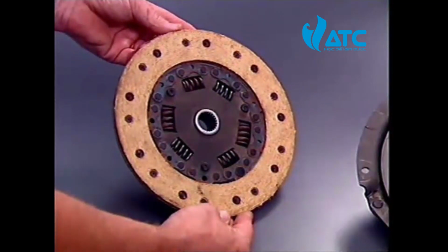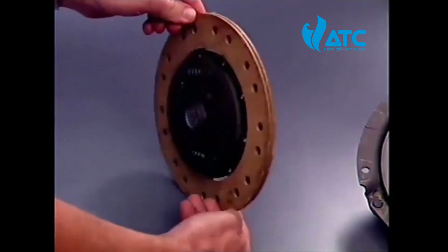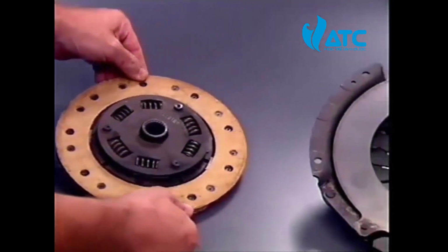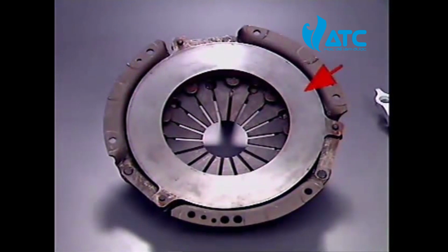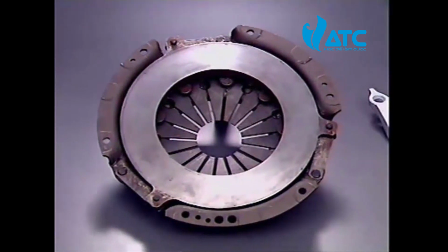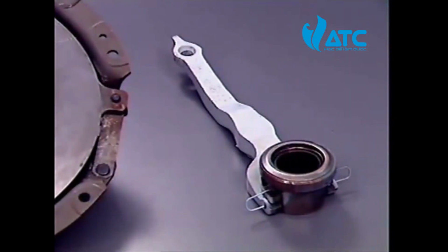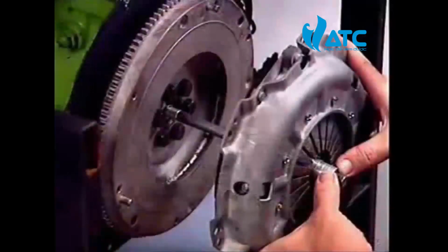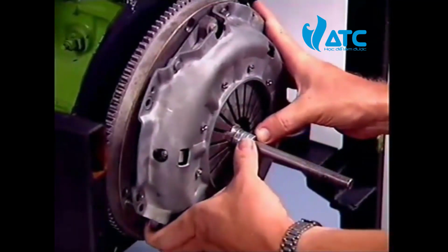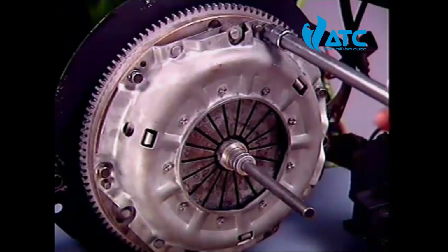The clutch unit consists of a friction-type disc with two friction facings and a central splined hub, a pressure plate assembly consisting of a pressed steel cover, a pressure plate with a machined flat face and a segmented diaphragm spring, and a release bearing and operating fork. The friction disc is sandwiched between the machined surfaces of the flywheel and the pressure plate when the pressure plate is bolted to the outer edge of the flywheel face.